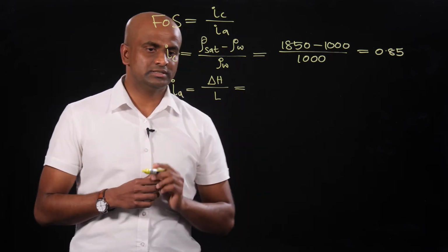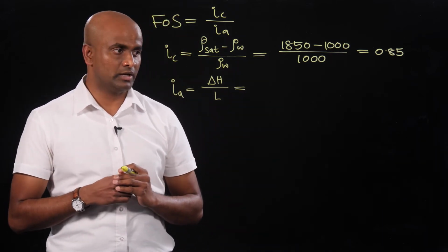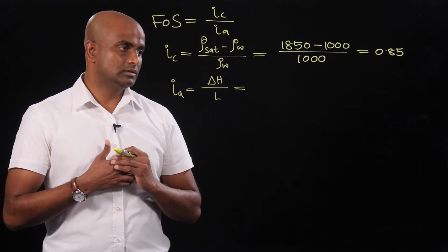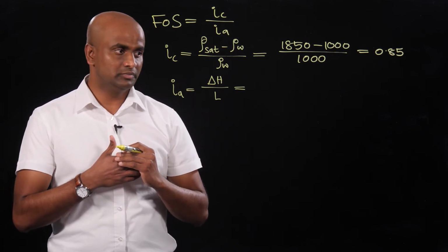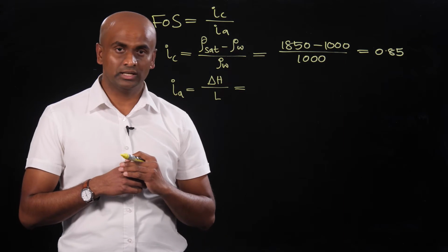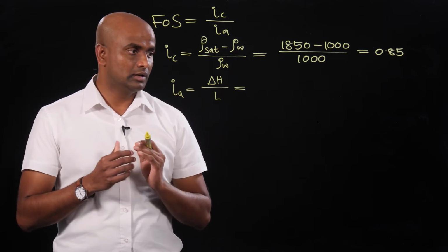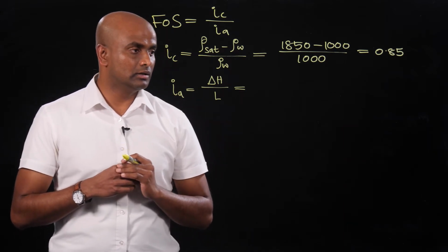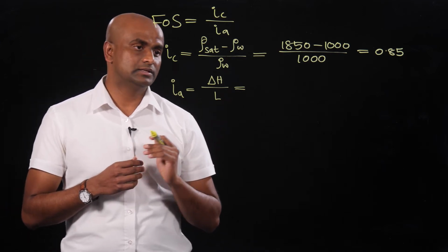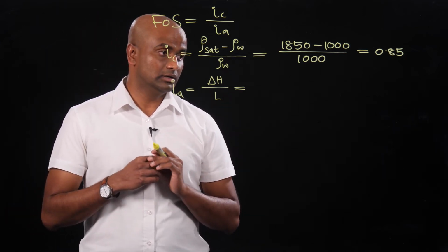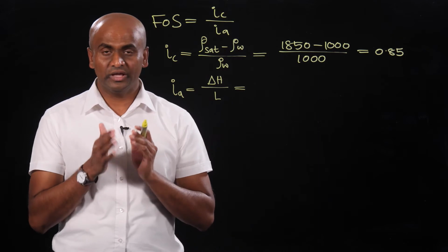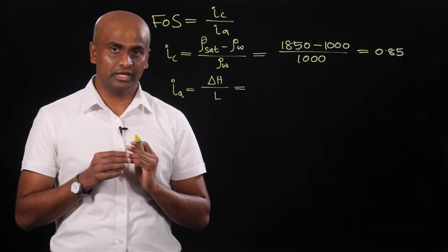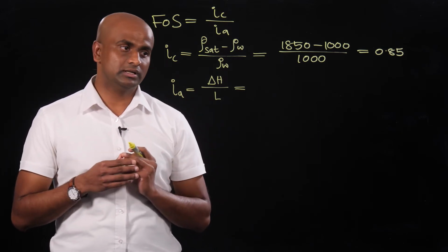So the head difference across the exit square is the difference between total head between the two equipotential lines that the exit square covers. The total head difference between any two equipotential lines is the same. That's why they are called equipotential lines.